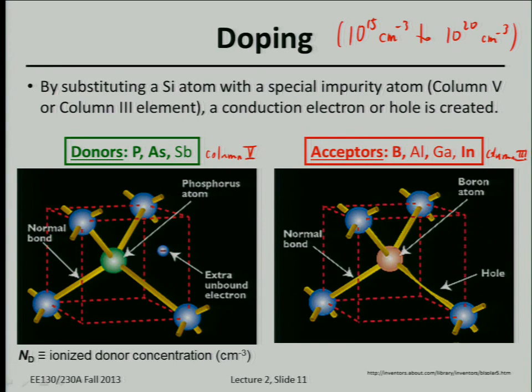Okay? So every time, ideally, you introduce a boron atom into a silicon lattice site, you are actually contributing a hole to the silicon lattice. Does that make sense? In other words, you're taking away a conduction electron from the lattice. Okay, so what kind of a seat would actually be a good model for an acceptor atom?